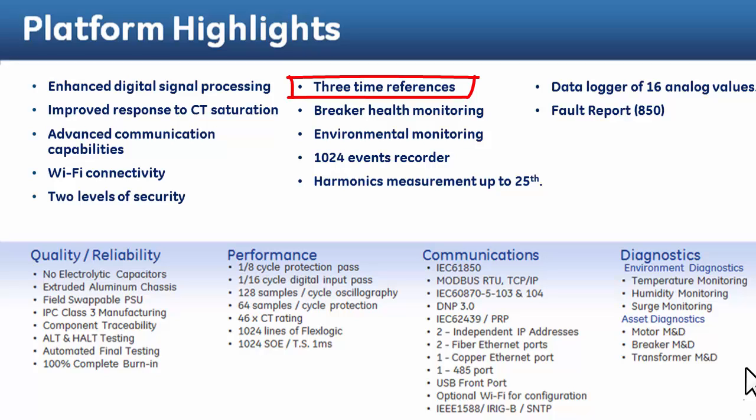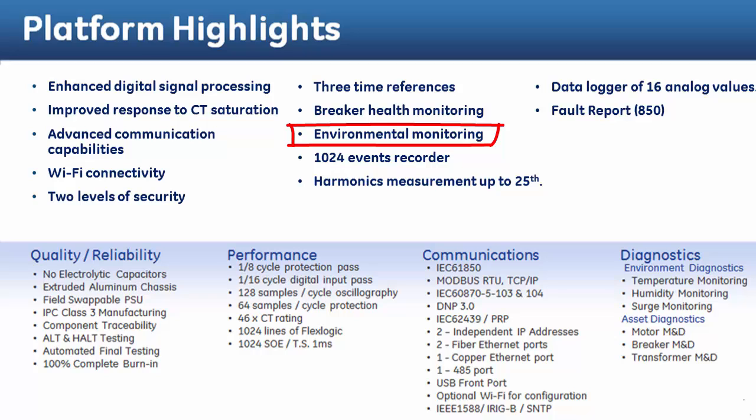3 time references are SNTP, IRIG-B, and IEEE 1588. The breaker health monitors overcurrent times, trip circuit, spring charging time, per phase arcing current, and trip counters. Patented environmental monitor measures and provides operating condition information and diagnostic information, which helps to reduce system downtime.